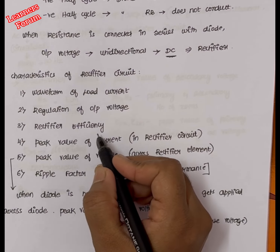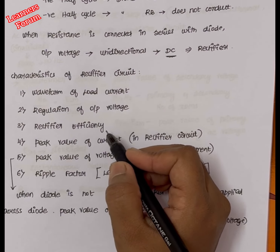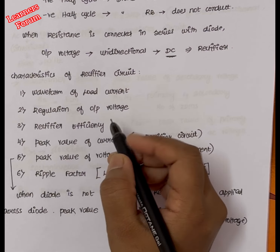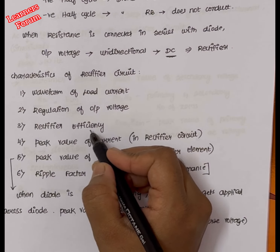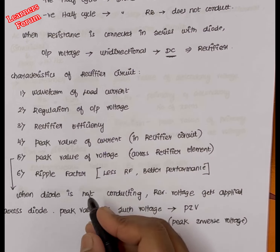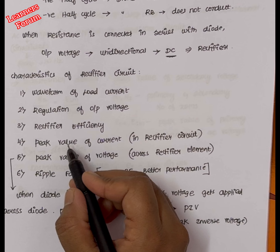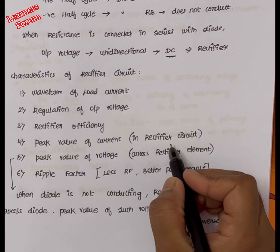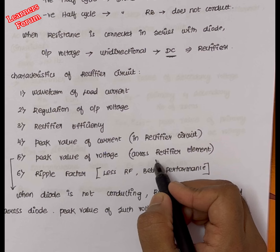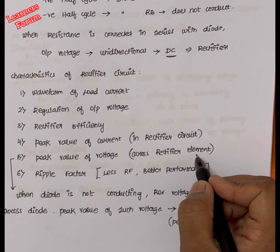Third is rectifier efficiency. So how much output we are obtaining and how much input we have applied. The ratio will be taken under rectifier efficiency. So we have to calculate the efficiency, based on which we can judge the performance of the rectifier circuit. Fourth and fifth are peak value of current and peak value of voltage. Peak value of current will be calculated in the rectifier circuit, whereas peak value of voltage will be calculated across the rectifier element. Here we are using the rectifier element as a diode.